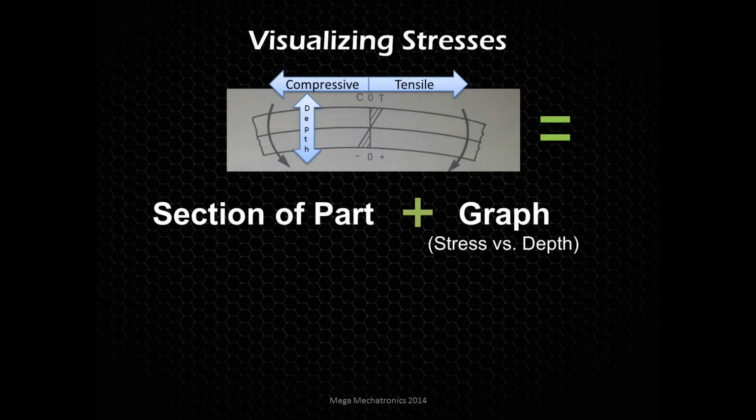You can almost think of that as the pivot point. This is a very symmetrical example as well, but we're just trying to get the idea across. So we have our tensile up there, and then we're moving to the bottom side. And obviously, at the very bottom edge is the maximum compressive stress, which just happens to be at the very surface.